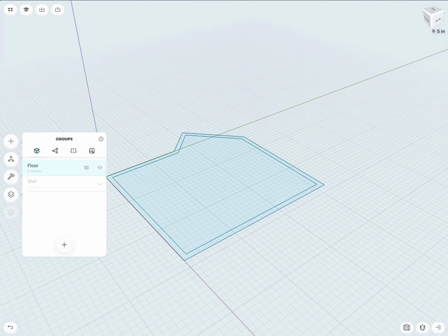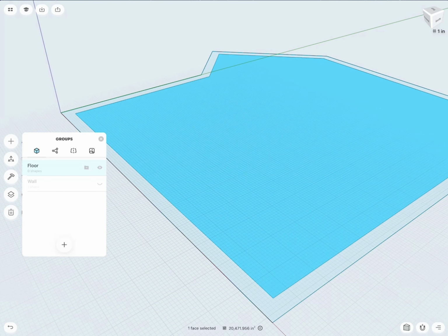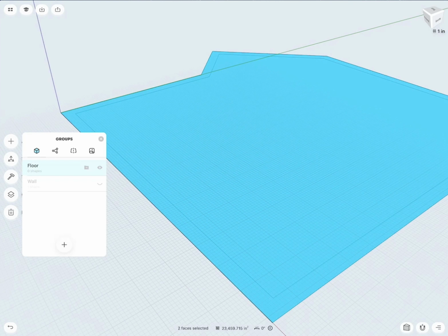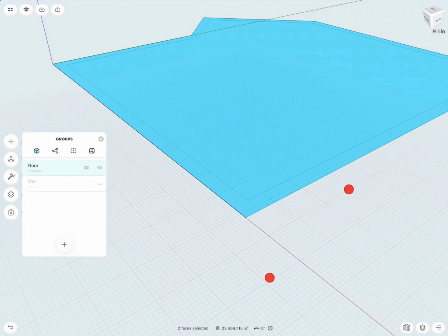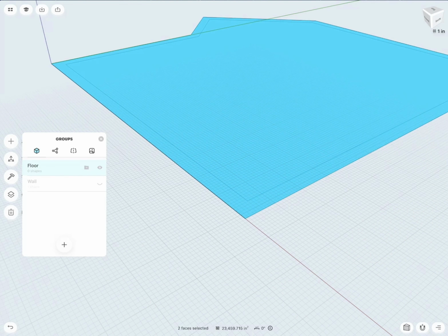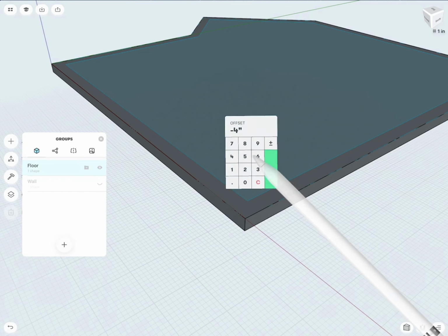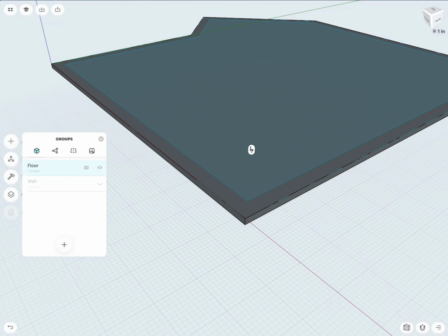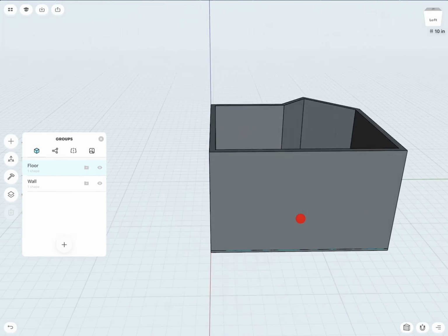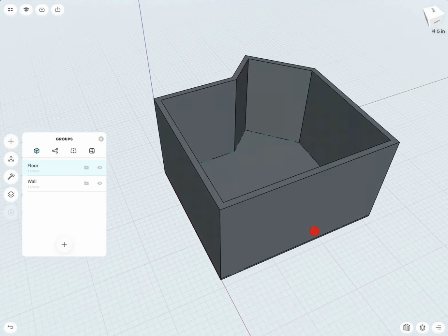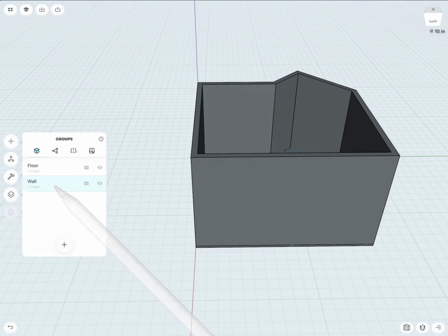And I can create the base this sits on. And let's say we will create an artificial 2-inch surface or slab this one sits on. So with the pencil, as you saw, I selected both areas, and then again tap, drag down, let's say 2 inches. Very good. There. Very nice. Okay, let's go back to the wall. I hide the floor for the moment.